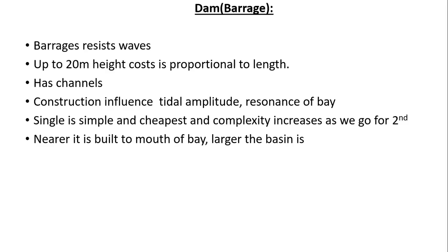Up to a height of 20 meters, the cost will be proportional to the length, as it is not changed by the need to build a dam wall to withstand high hydrostatic pressure. When the height exceeds 20 meters, the cost increases faster with the length. Most tidal power plants do not have heads exceeding 20 meters, all will be below 20 meters only. This barrage needs to provide channels for the turbines in stressed or reinforced concrete.